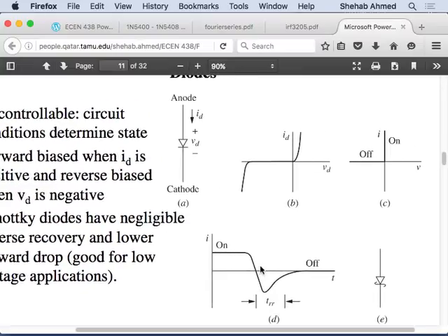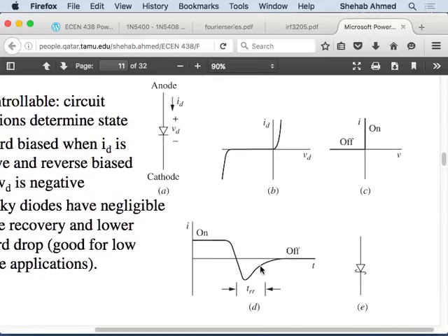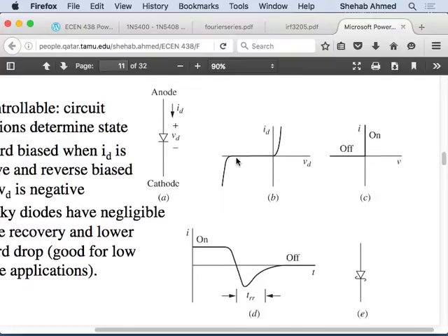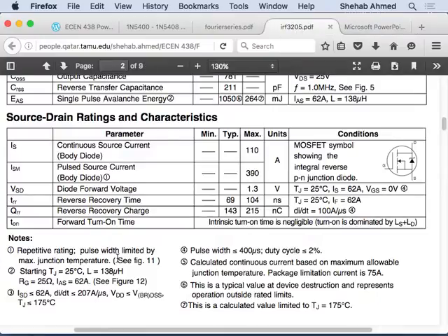Okay. Yes, sir. Does the backward voltage affect the recovery time? So if I apply backward voltage on the diode to turn it off right there in the middle of the analysis, does that shorten the recovery time? A certain amount of backward voltage? I don't believe it does, because there is a certain amount of charge that needs to be removed, and this reverse recovery time is a fixed amount of time. I think it's for a specific value of current.